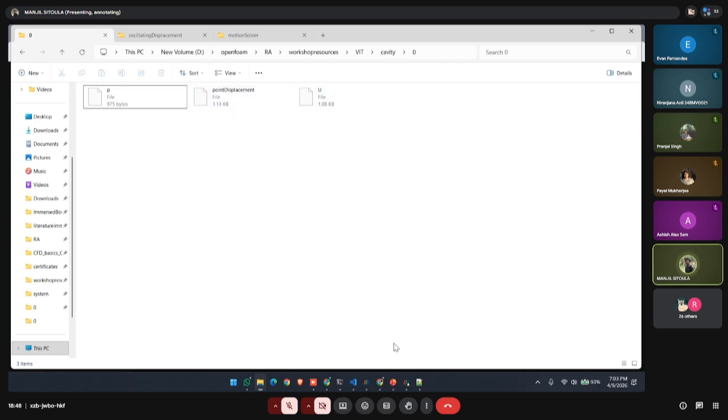In the next case that I had shown you, the laminar flow, we'll be looking at the results also by solving the case. But in this case, I'm just teaching how to start from scratch and then set up the case for dynamic mesh: what files are required, where we need to keep those files, and how we know what inputs we need to provide. So this first is the case setup. We'll just be learning how to set up this case, but we won't be running the solver.